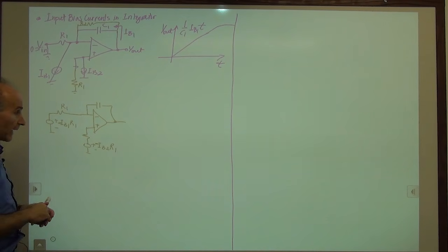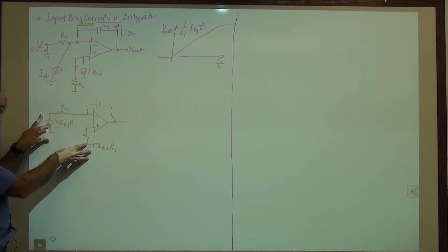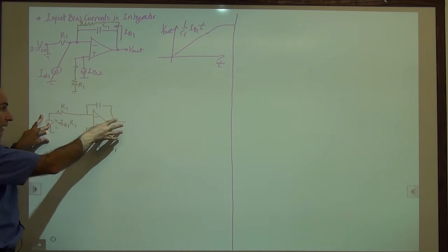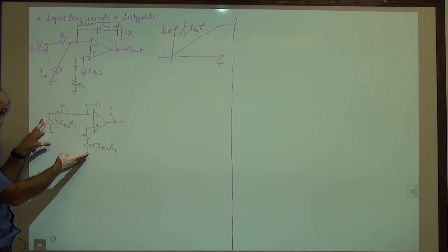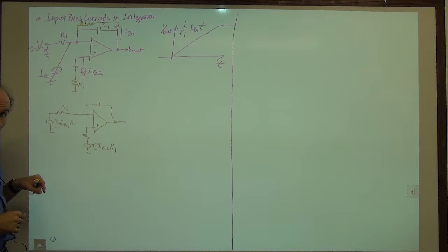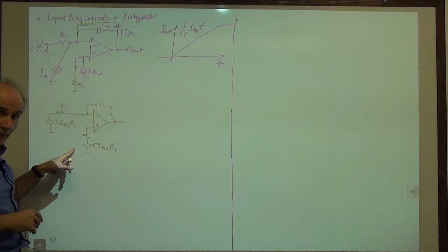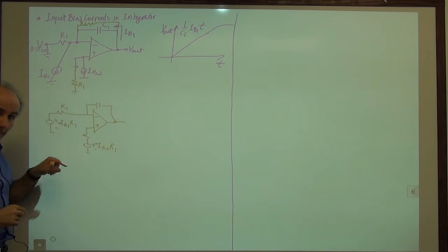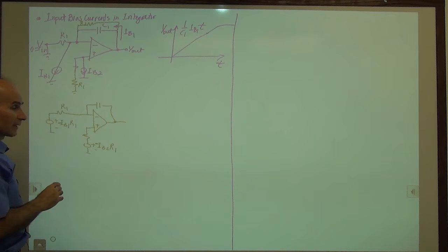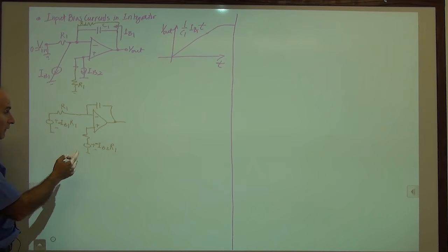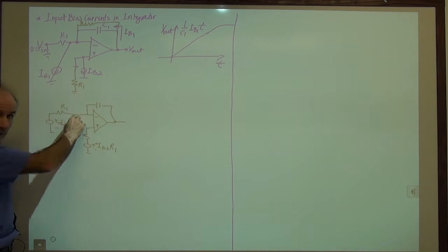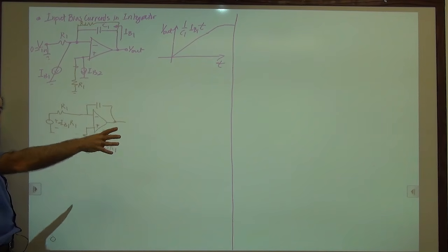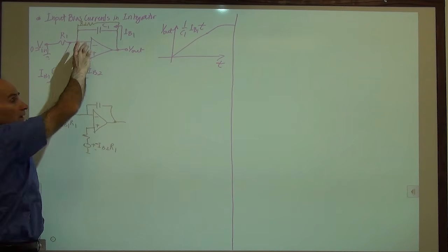So what we are thinking is that because these two voltages are equal, the integrator doesn't see any difference, so it doesn't integrate. So yes, we could try to do that, and usually we do that with bipolar op amps. But keep in mind that if there's a slight difference between IB1 and IB2, we still integrate. So the only reliable solution is to use this resistor.